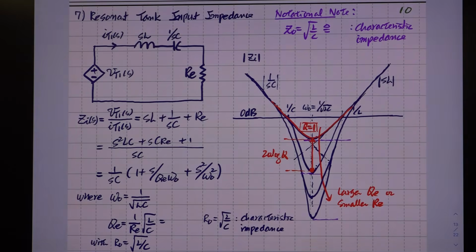As I said, this is the AC model, representing the sinusoidal response of the tank network. The difference from the real network is that R load has been modified from the real R. Except for that, this model predicts everything about the operation of this resonant tank. These are sinusoidal waveforms, but they can be easily transferred to DC by just scaling the magnitude. You know that, right?